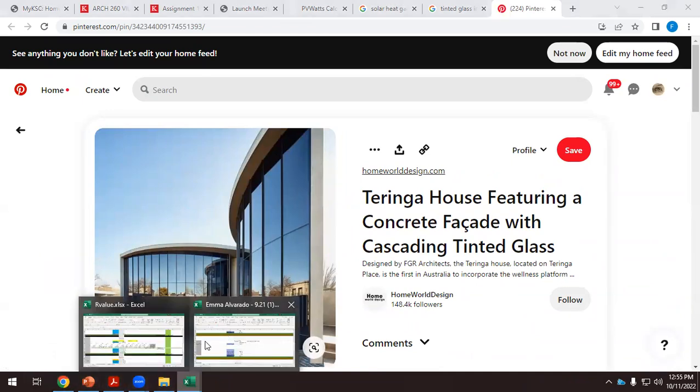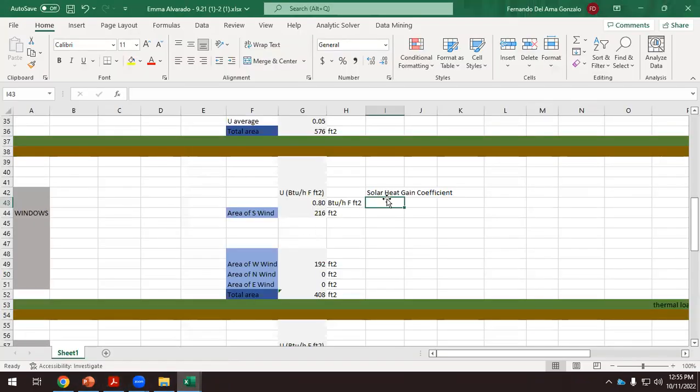And in this Excel file, now we have a field here with the solar heat gain coefficient. So if it's quite high, like 80%, we can type 0.8. This solar heat gain coefficient goes from 0 to 1. 0 is not transparent. 1 means that it's 100% transparent. No glass, it's 100% transparent. Okay, so it can be 0.9, 0.95, but we hardly ever have 1 as a solar heat gain coefficient. So for these glasses that we're used to, we have like 0.75, 0.8, something like that.